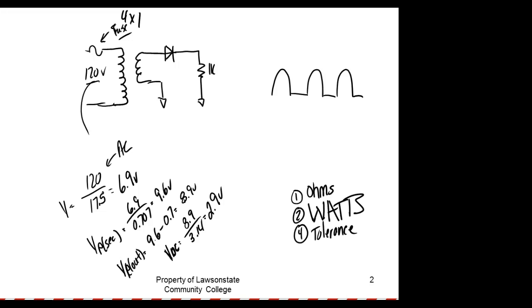Yeah, so 15 volts squared divided by 100. That's 2.25 watts, and they were putting a little quarter-watt resistor up there. What was it doing? It burned them up as fast as they could put them in. And they were coming up and saying, something's wrong with my power supply. It keeps burning up resistors.